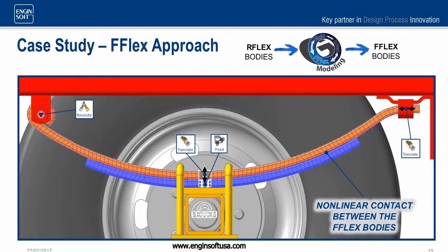This is just one single contact that is linking the entire shared faces of the two bodies. Also, I have removed the fixed joint supporting the upper part of the lift spring, and instead I have applied a translational joint that allows the upper part of the lift spring to translate vertically and so press on the lower part.